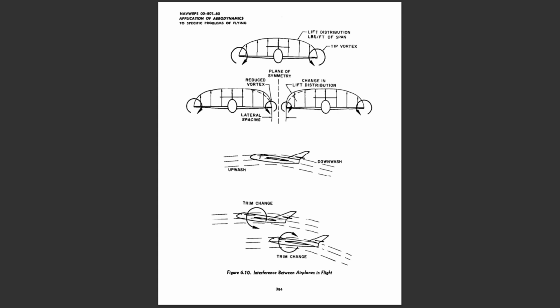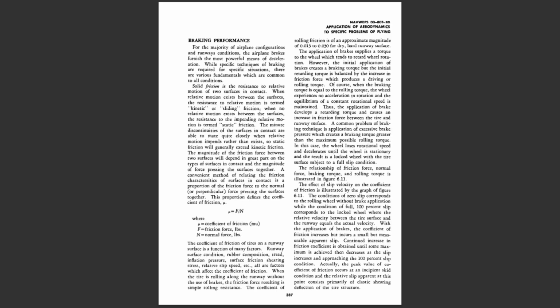In addition to the forms of interference previously mentioned, there exists the possibility of strong interference between airplanes in supersonic flight. In this case, the shock waves from one airplane may strongly affect the pressure distribution and rolling, yawing, and pitching moments of an adjacent airplane. It is difficult to express general relationships of the effect except that the magnitude of the effects will be greatest when in close proximity at low altitude and high q. Generally, the trailing airplane will be most affected.